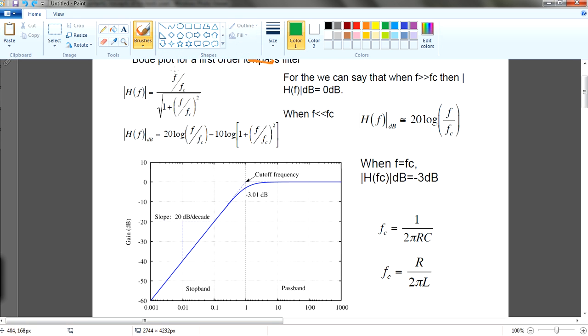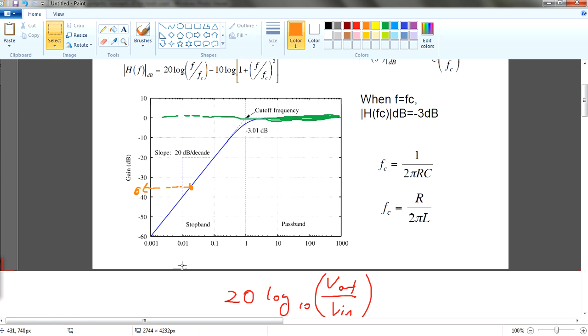So let's say I give you this frequency, and if your frequency is larger than your cutoff frequency, alright, you can actually draw this one. You deduce that your frequency is at this point, right? So if your given frequency is lesser than your cutoff frequency, you will have maybe some frequency at this point, you'll know that okay, you have this amount of gain, right? And then from here you can calculate your gain and such. So they will not give you any gain at the moment. They will only give you the frequency, and then they ask you to find the gain.